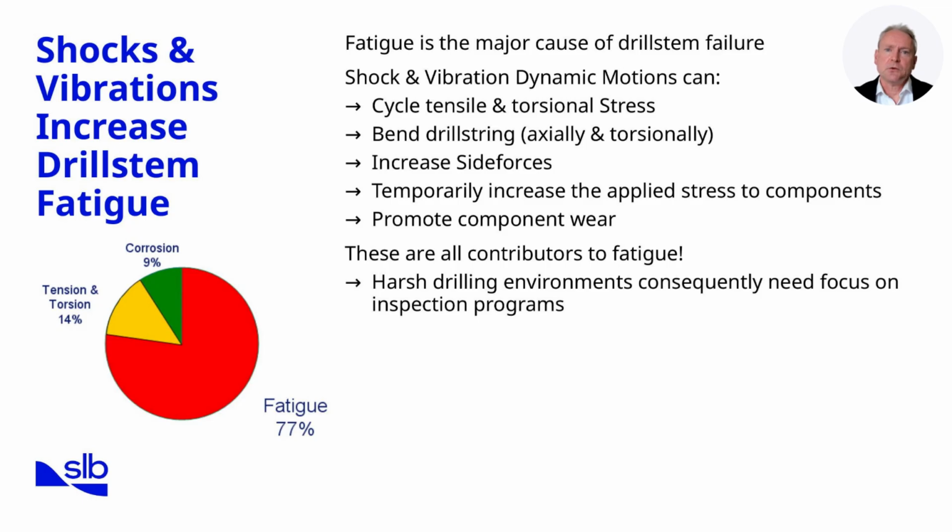Fatigue is the leading cause of drill stem failure, and shocks and vibrations significantly accelerate that process. Dynamic motion during vibration cycles the drill string through tensile and torsional stresses. This repeated loading weakens the steel over time, even if the applied stress is below yield strength. Vibration also bends the drill string axially and torsionally, creating additional side forces. Each bending cycle adds to the cumulative fatigue damage.